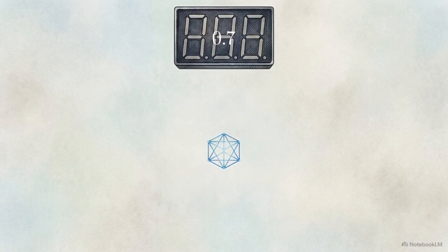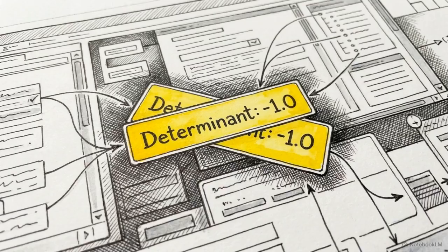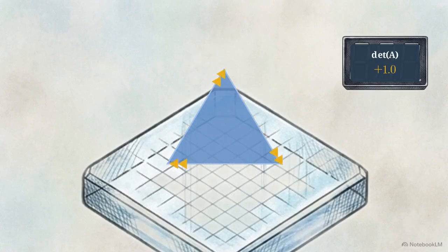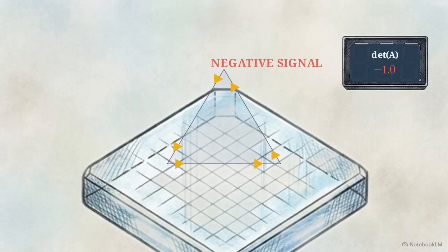If the determinant drops below 0, the geometry mathematically inverts. The asset collapses through itself, effectively flipping inside out. Rendering engines use this negative determinant as a deliberate signal. It tells the software to reverse vertex winding orders for backface culling, optimizing what the camera actually sees.